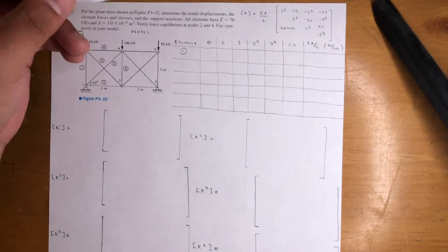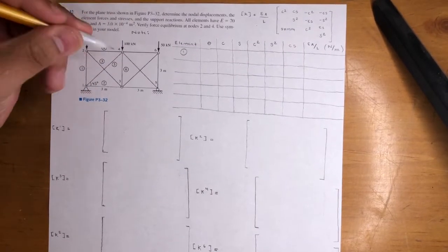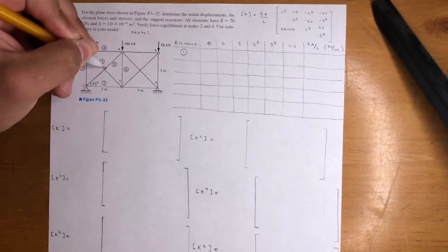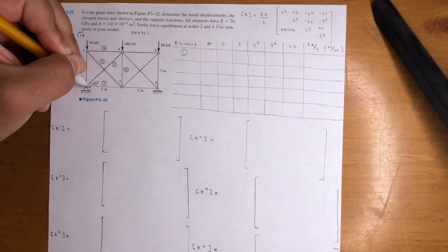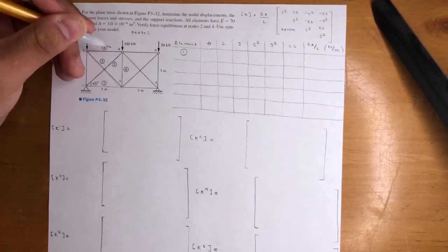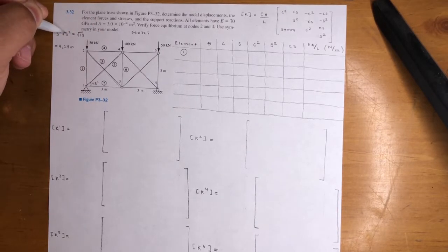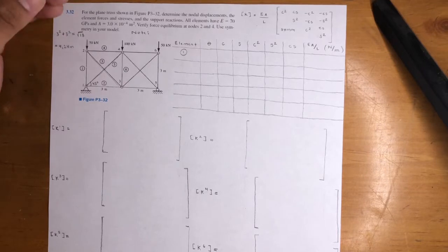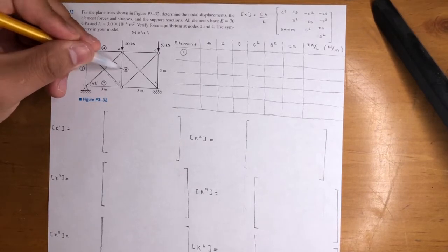Alright, so I kind of already laid all this out, just to save time because this problem is very long. I want to go ahead and find the length of these two bars that go this way because we're going to need them. Everything's 3 meters going sideways, 4 and 2, and 1 and 6 are also 3 meters. So for these two, you do Pythagorean theorem, 3 squared plus 3 squared is equal to something squared, which is just radical 18, and that answer was 4.24. So that's the length for bars 3 and 5. So we have 6 elements total.